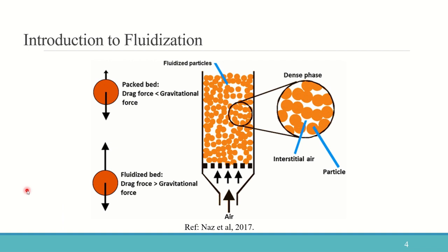Okay, let us forget everything and we'll start fresh. So what are fluidized beds? Fluidized beds are nothing but where we pass the fluid inside the solid packed bed, and those particles start to behave like a fluid, that is, they start to move. When will this happen? When we are passing the fluid at a sufficiently higher velocity. At low velocity the particles would not be moving, whereas at higher velocity those particles would be moving.